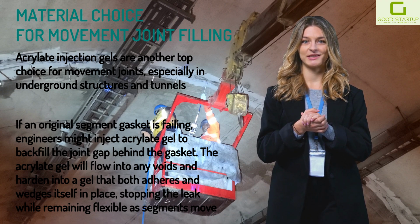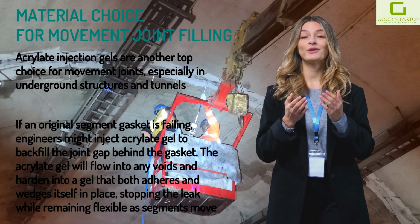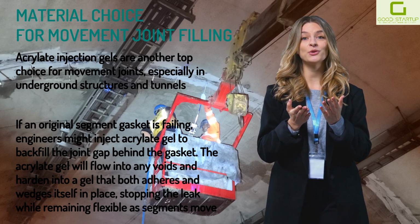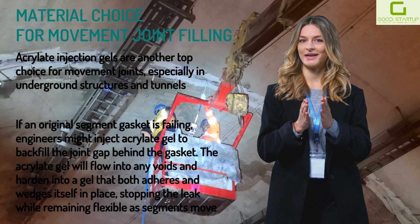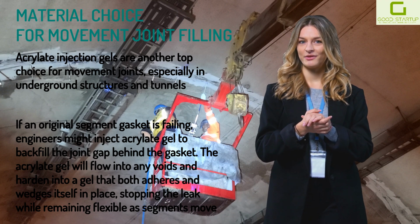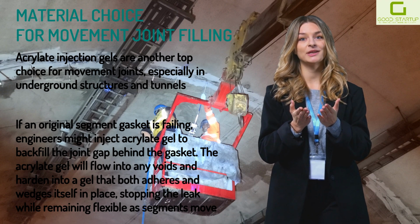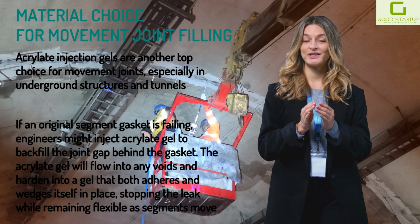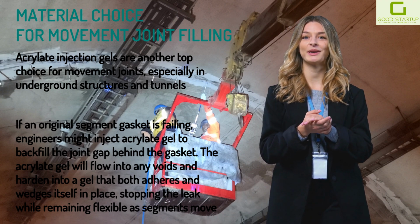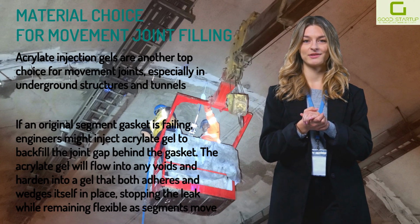Additionally, acrylates have adjustable set times. For long joints, a slower gel time might be used to ensure the material propagates the length of the joint before gelling. Acrylate gels and PU gels are sometimes used in tandem. A fast foaming PU can initially stop a high flow leak. Then a slower acrylate gel is injected to permanently seal the joint and fill any remaining cavities. This two-step approach is common in waterproofing practice, though the specifics depend on site conditions.